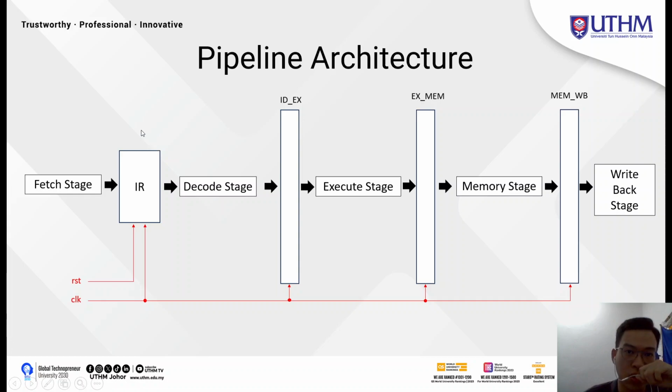For this project, since the instruction register (IR) and the pipeline register are both responsible for holding the data that passes through them, therefore I use the instruction register instead of the pipeline register, and I place it in between the instruction fetch stage and the instruction decode stage.